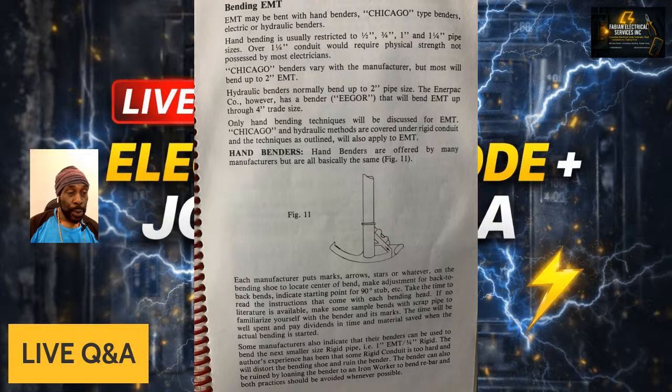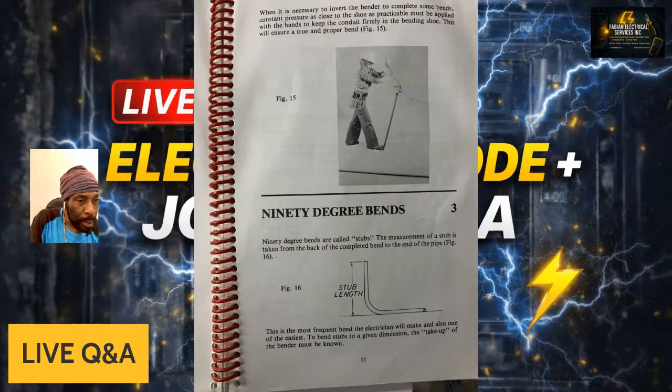So I'm going to remove that, and I'm going to go on to the next photo here. So again, that's another method of bending conduit. Basically, that's how I normally like to bend my pipes. The reason why is I have full control of the pipe and the bender. Having full control of the pipe and the bender is important when you start to bend conduit.